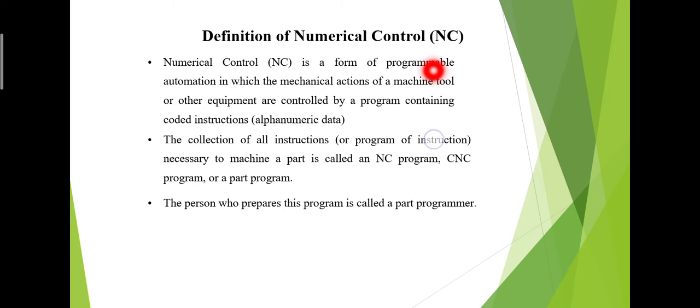Because NC technology brings the following main advantages. For example, best control of cutting tools. The main advantage of an NC machine is the increased and accurate control of cutting tools, which would be manually very difficult. Consider an example of a circular or parabolic motion of a machine tool, where movement along both the x-axis and y-axis needs to be simultaneously controlled, while it is very difficult to do this on a conventional machine.